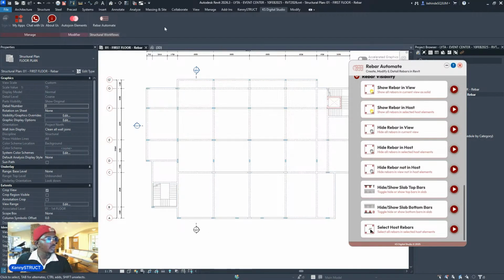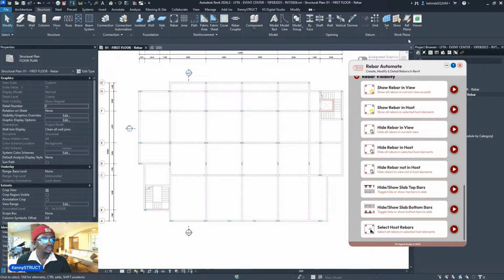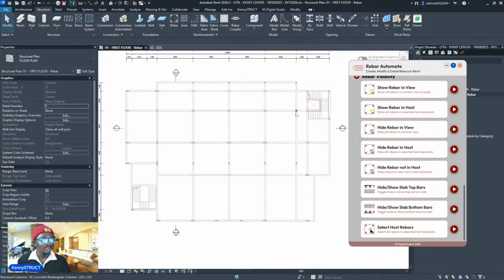One thing we try to do here is to give the engineer control. There's a way you can quickly do this. You can use reference planes in Revit to create the extensions of your top bars. By what extension into the panels do you want your top bars to go? Based on design, usually it's 1/3 of the slab panel span. So that's like 0.3 of the span.